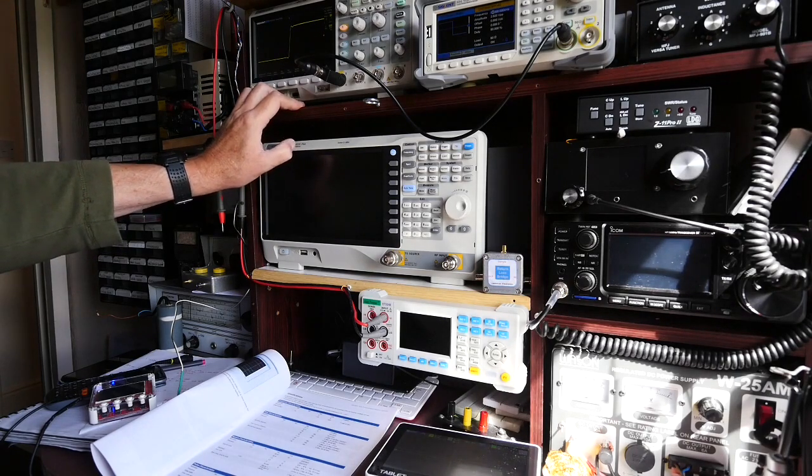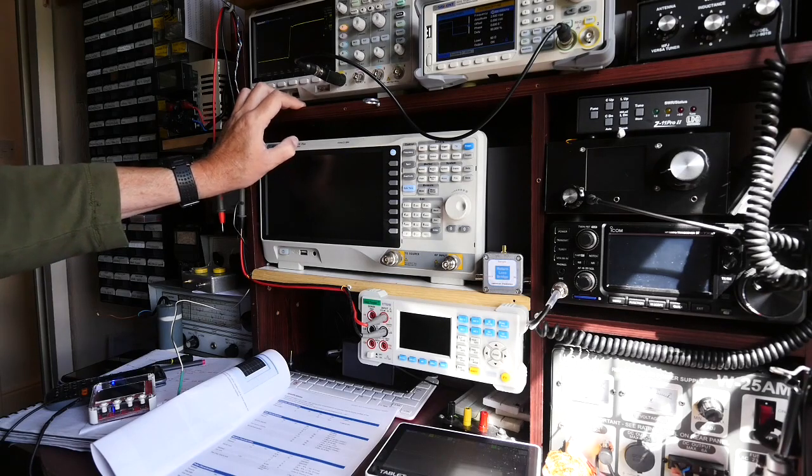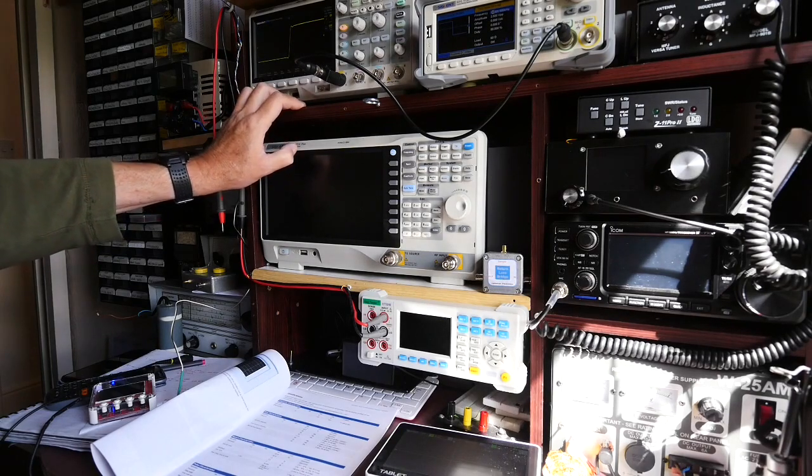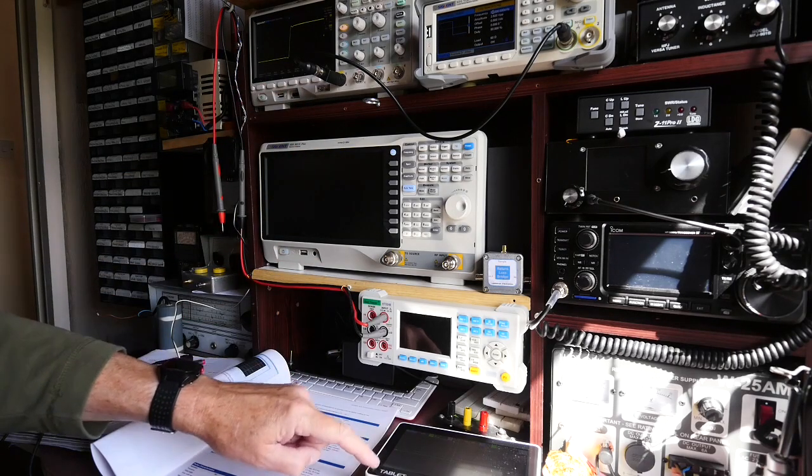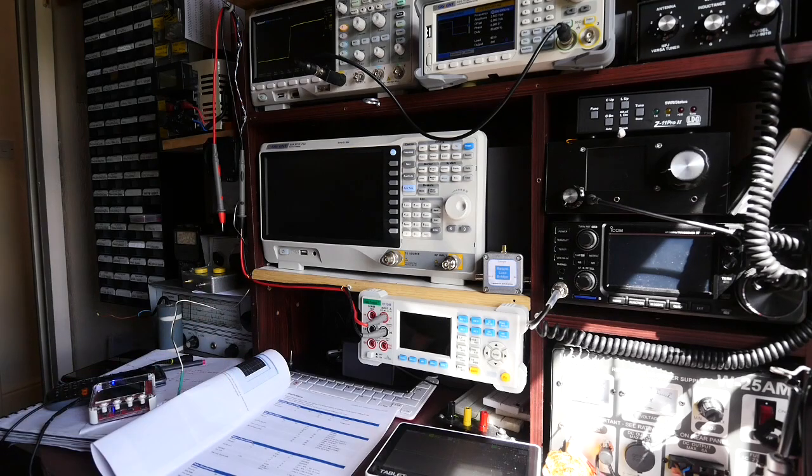It's done about 100 measurements now, and I'm getting a mean of about 4.05 nanoseconds. So you can see straight away a very, very different rise time measurement on the Siglent compared to the tablet. We'll look at what that does in terms of numbers in a moment or two. But the reason I've picked 16 kilohertz has got some logic to it, and that's because if you look at